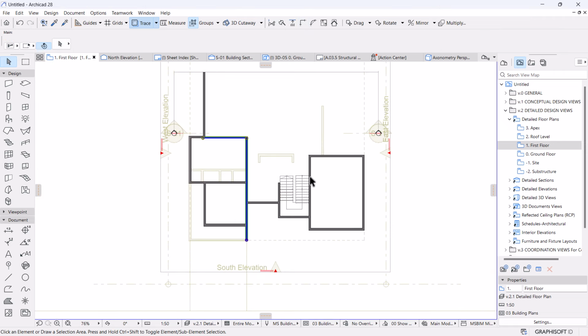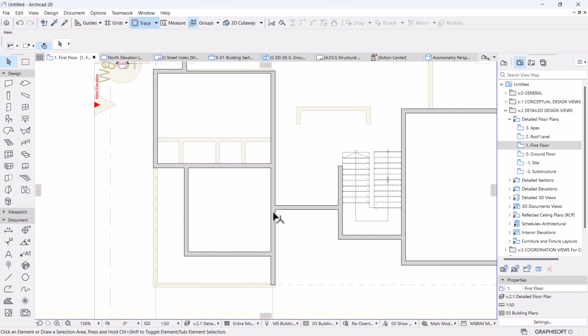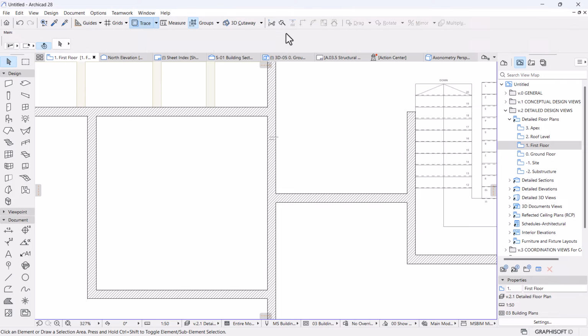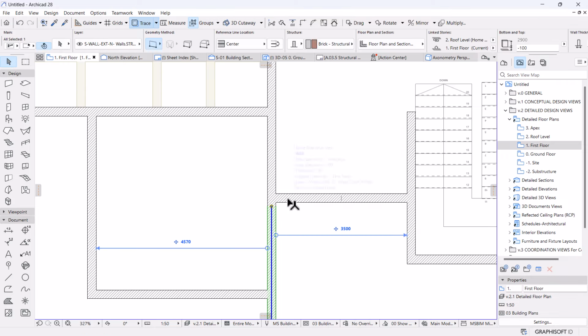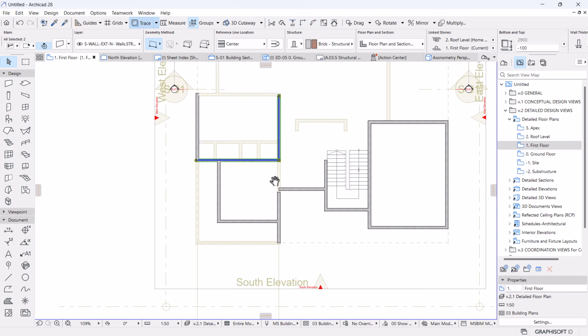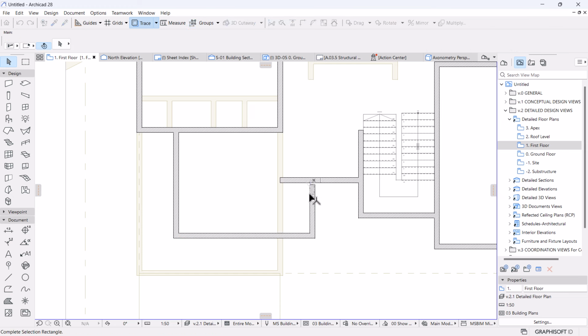All right. Okay, so like I said, I want to have a double volume here, but I want to create a bit of an overhang from the top, which is this wall. So I can quickly split these two walls like that, and this will be filleted there, yes. And then with the overhang, I would move it by 1.5. So that will be the overhang. So I now can intersect to clean up these two walls like that.